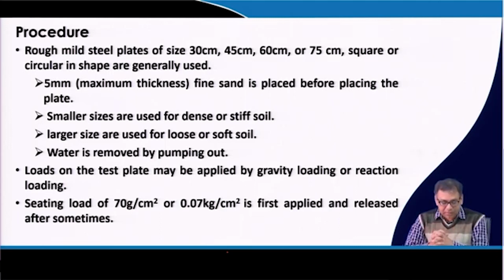When you do the plate test, before you place the plate on the foundation bed or the soil, you place a 5 millimeter thick sand pad, then you place the plate. Okay. The smaller size plates are used for dense or stiff soil, and the larger size is used for loose and soft soil. If there is water within your test pit, you just pump the water out and remove it from the pit. The loads are given through the reaction frame.